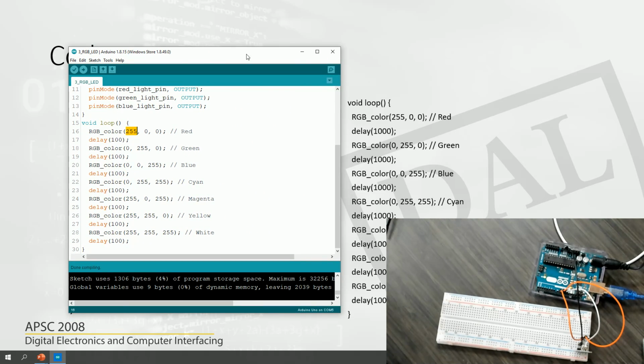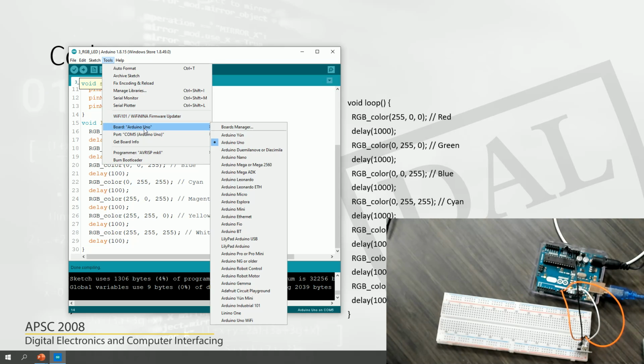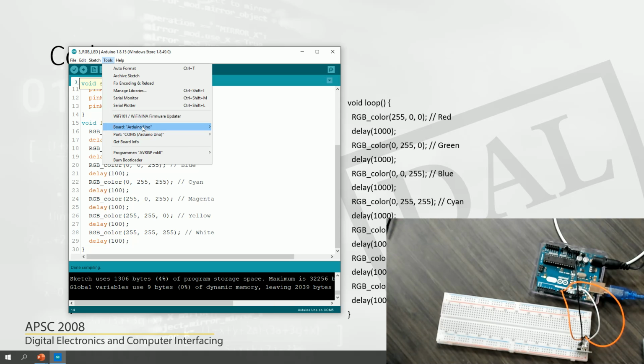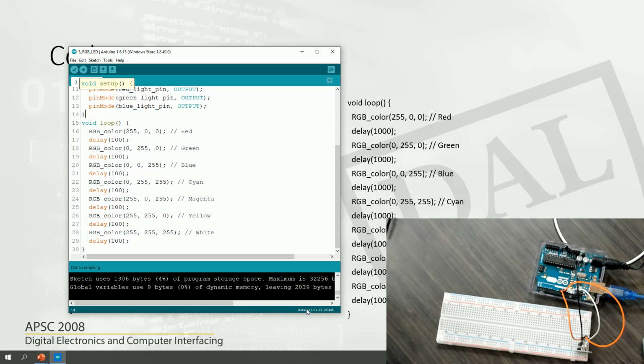I closed the sketch I opened early on, and then for some reason, again, the default board was the Arduino Mega, it was selected for some reason, but I've changed that back into Arduino Uno, and make sure you have the Arduino Uno connected to the COM port. So you see this display indicates that the Arduino Uno board is connected to COM port 5. So I've made sure of that as well. So I've compiled it now. So I'm just running it.